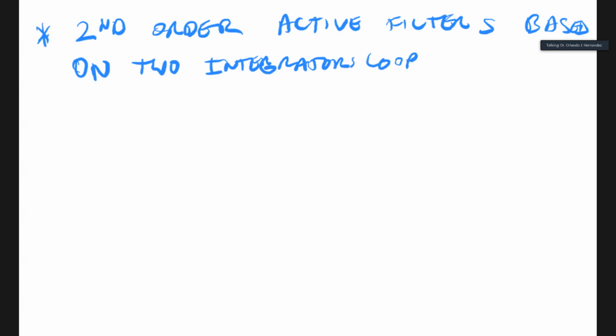So basically what we did is we define our transfer function as the high pass response versus our input voltage, and we know that for a high pass, we're still talking about a second order, so the best high pass that we can have is some scale factor with 2 zeros at 0, because we really want to reject the DC.